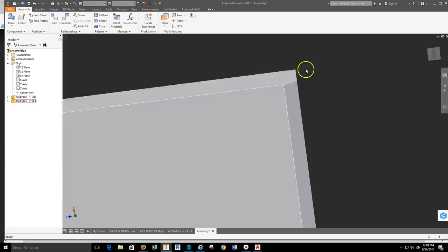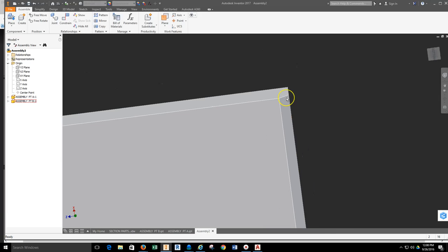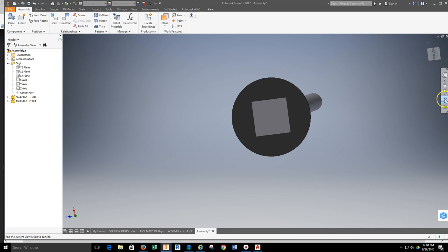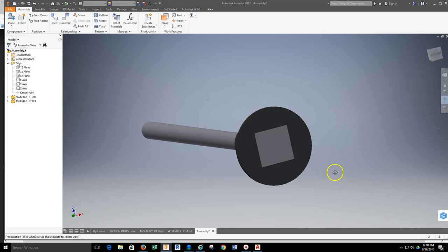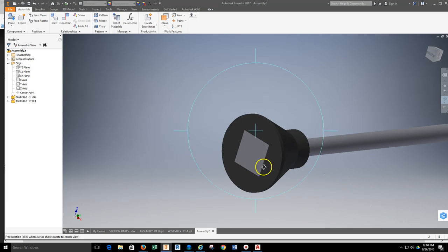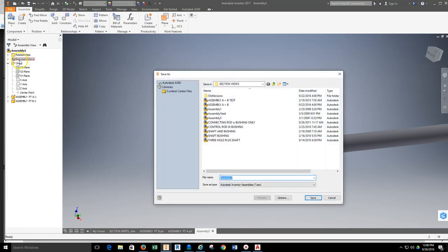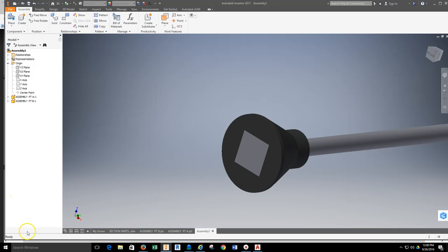And it's going to have space on all sides, knowing that this thing has been centered perfectly. So now that is complete. The simple insert constraint works very well with putting this part together. I can go ahead and do a File, Save As, and then save this back to my TechEd server space, and now I have a saved assembly. I would save it as assembly A plus B, or whatever the part names will become later. Save those as the assembly and the parts themselves.